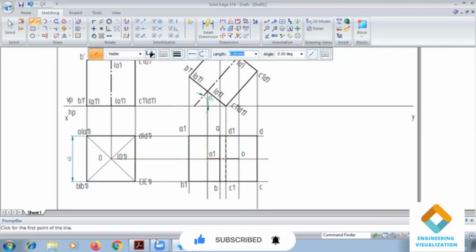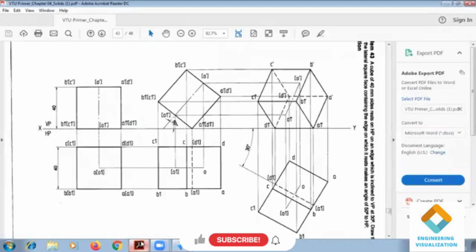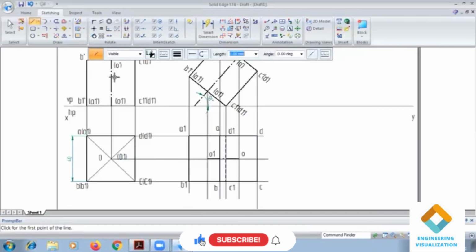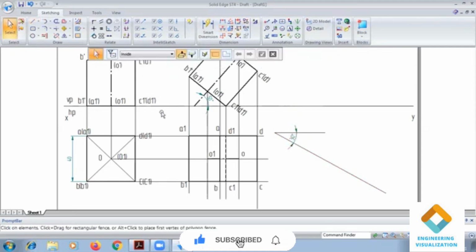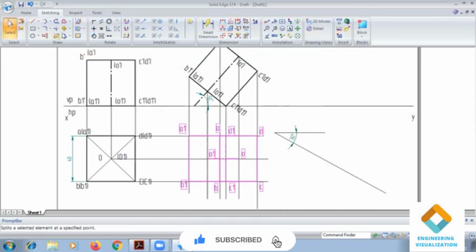Okay. Now the angle of inclination to VP is 30 degrees. So draw a line and here I will give angle minus 30. Now we have to select this whole thing with respect to resting edge D1.